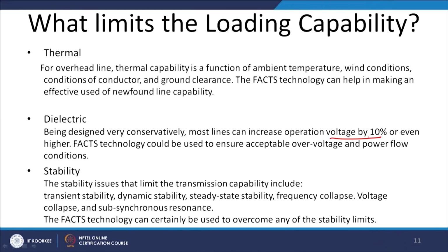In the same way, the dielectric limit comes with the voltage level, because the dielectric limit also works on the basis of the voltage rating, and it too is set for the worst environmental condition. For a normal operating condition, we can easily increase the voltage limit by 10%, thus FACTS enables us to smoothly carry 10% extra power without much change in the network. And stability is a very big issue in the power system. There are different kinds of stabilities.